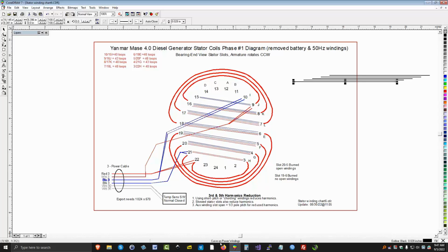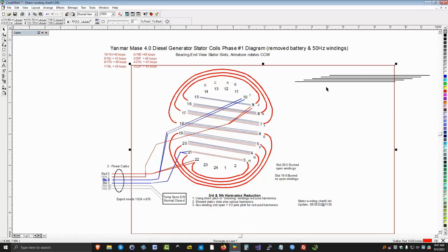There's only one curve selected because the box doesn't include the edge of the second one. Let me redo that, make it more obvious. Okay, right there's the other thing I want to show you. I put this rectangle around the drawing so I can see where my limits are. And if you miss selecting on something, it's going to select what's behind this area. And what's behind this area is this box that I drew.